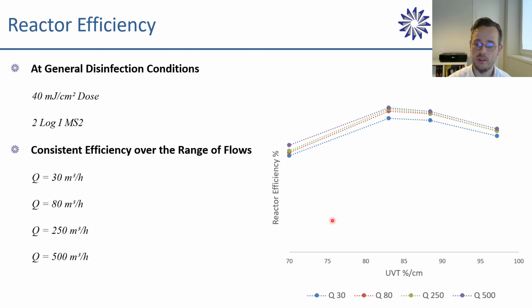And this bit we consider as an extended range of our reactor, so we don't expect it to be operating in that range very often or in many installations at all. But in the validation process, we did validate it down to that, just so we can offer the validated range for this reactor. If we were to design a reactor that's going to be permanently sitting for those UVTs, we can do that by selecting a different number of LEDs per ring, or changing the reflector design, or adjusting the reactor diameter, and then we would have moved the peak over here. But as I said, for this case study, I'm only interested in this particular reactor design.